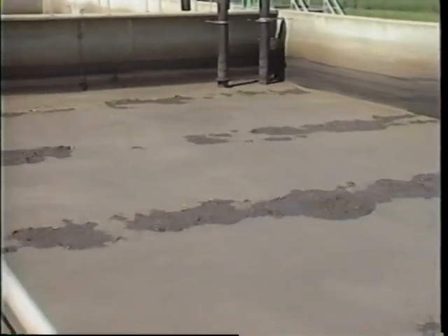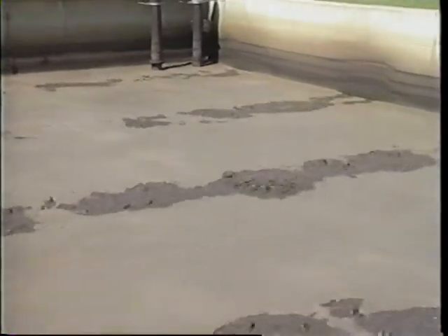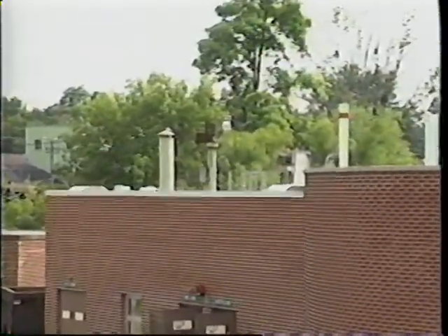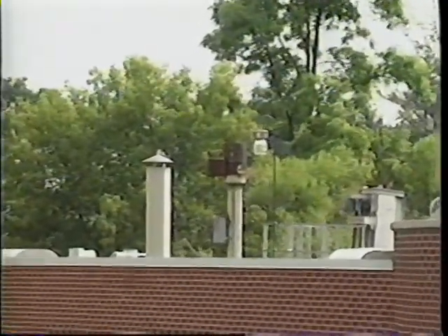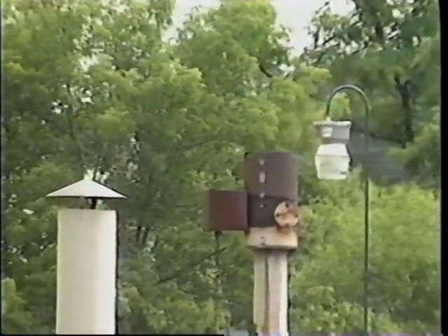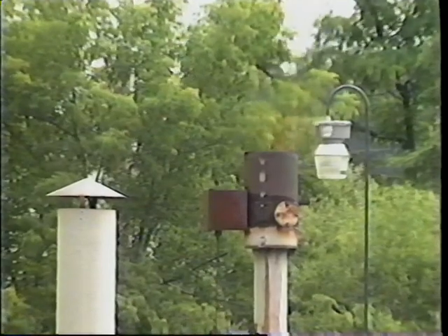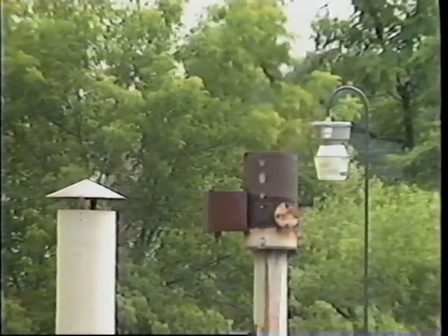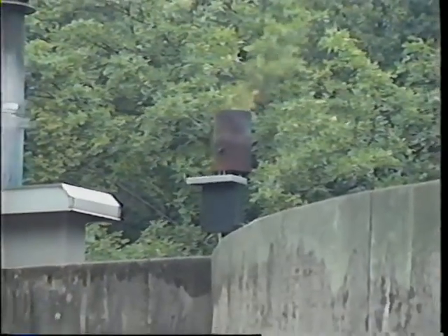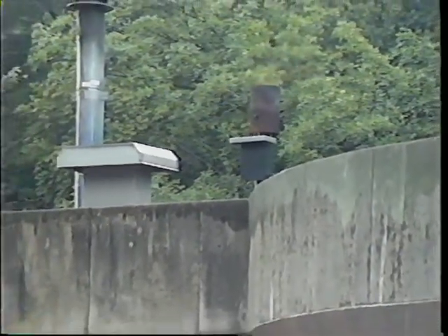As opposed to aerobic bacteria, which require dissolved oxygen, anaerobic bacteria thrive in an environment devoid of dissolved oxygen, which is derived chemically from their food supply. The result of the anaerobic bacteria eating the organic material in the biosolids is the production of carbon dioxide and methane gas. Biosolids are generally considered properly digested when approximately 50% of the organic matter has been consumed by this carefully controlled biological process.